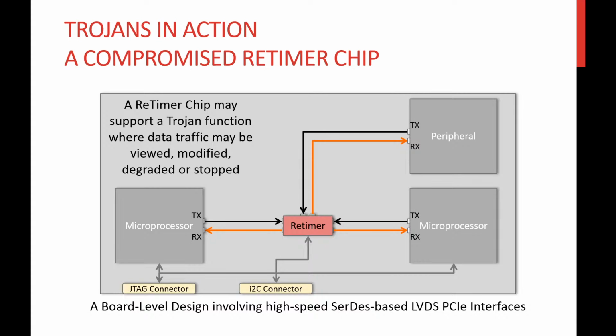That is the PHY, physical interface, and turns them into parallel data in a MAC, media access controller, in a serial to parallel operation. It also checks for correctness using the ECC, error correction codes. Then passes them back out through a MAC or PHY on the TX, and that's the transmit side, in the parallel to serial operation. So the retimer is the gatekeeper.